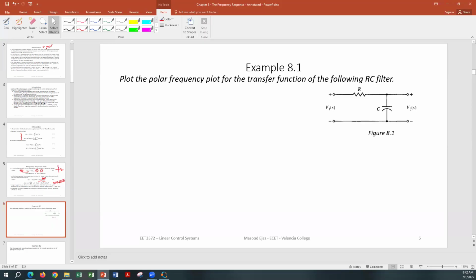So this is a low pass filter. Yes, you can memorize the location, but the reason it is a low pass filter is because the reactance of the capacitor acts differently for different frequencies. And that's what you have to observe. And that's what I mentioned a while ago: if you have energy storage components in a control system, those components are going to behave differently for different frequencies.